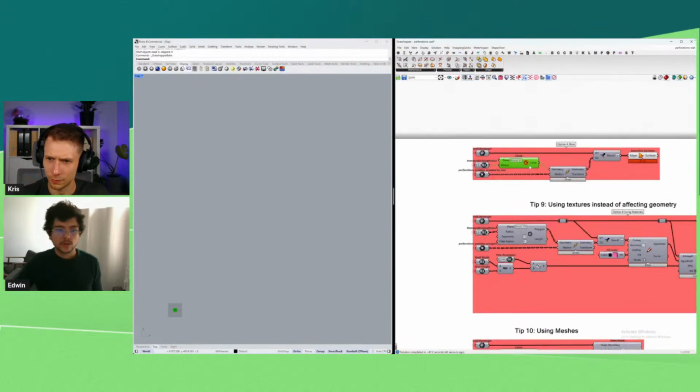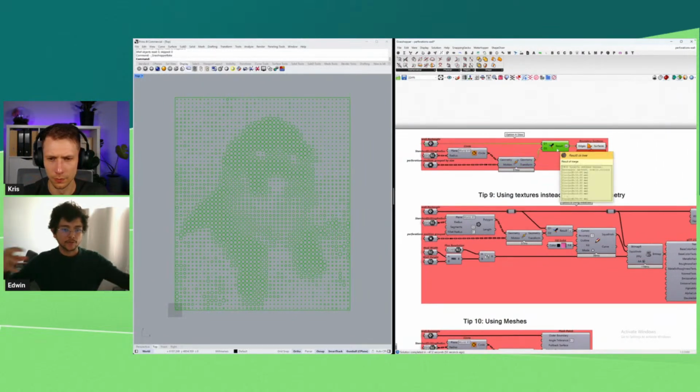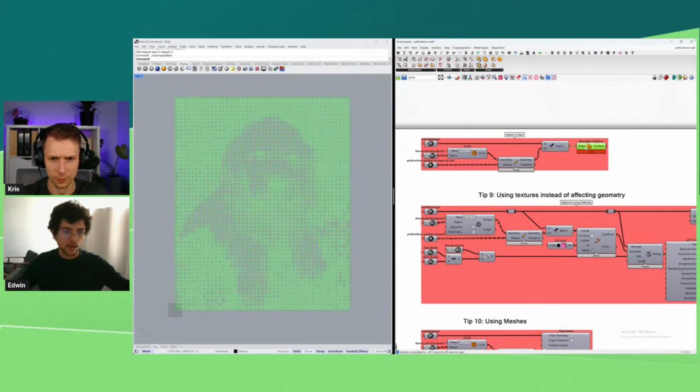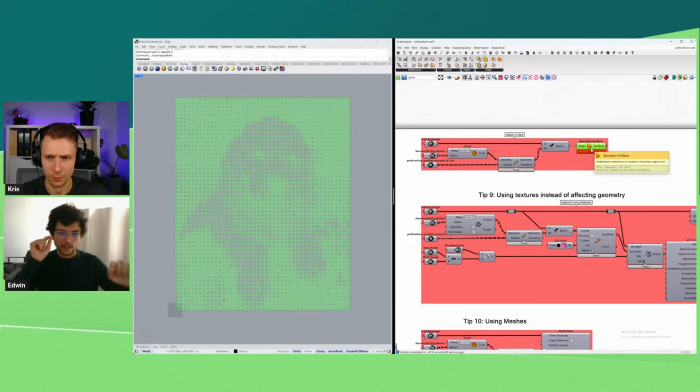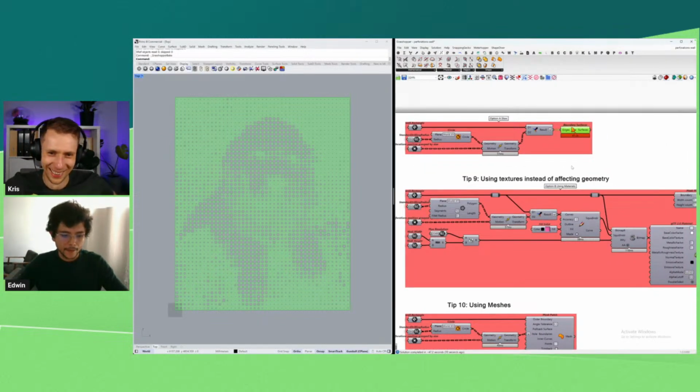Then with that, we end up with these circles, and this rectangle is the exterior of the wall. And then the idea is, okay, how do we fill the in-between? We need to know what is filled and what is a hole. The simplest way is to do a boundary surface. The boundary surface does the magic, and it is able to identify what is inside and creates the holes. This is how I would do that. Correct.